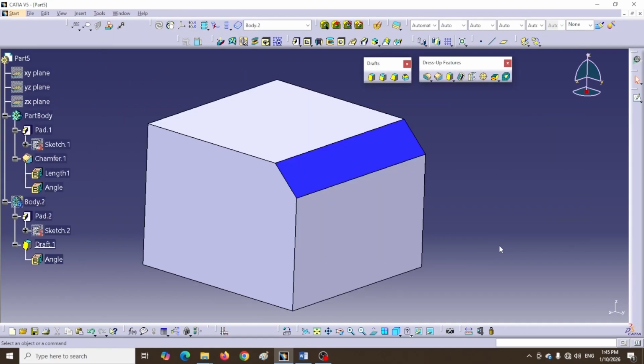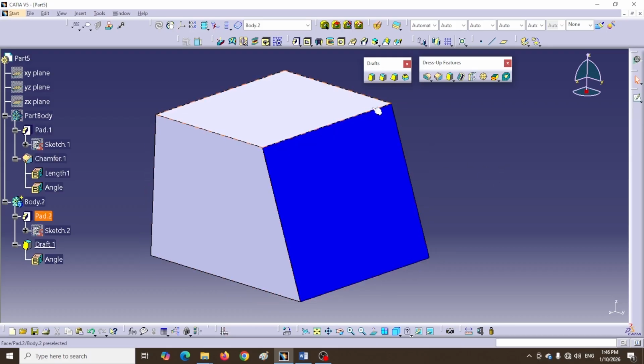The chamfer tools we use to bevel an edge. There we would cut away parts of the surfaces adjacent to the selected edge. Then we replace the cut part with a new surface. Here we work with an entire surface. We slant the whole surface.